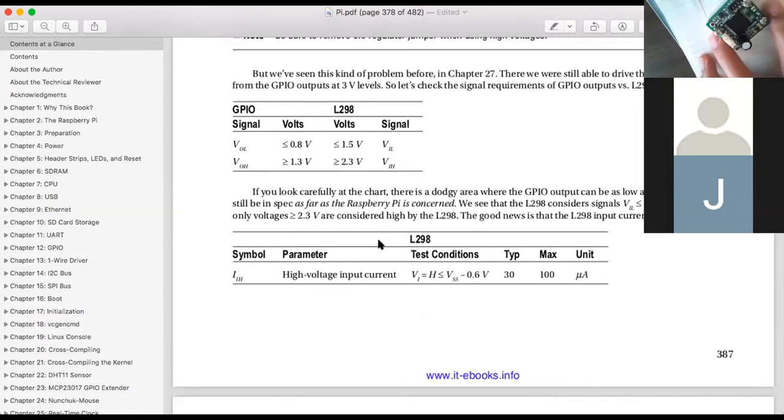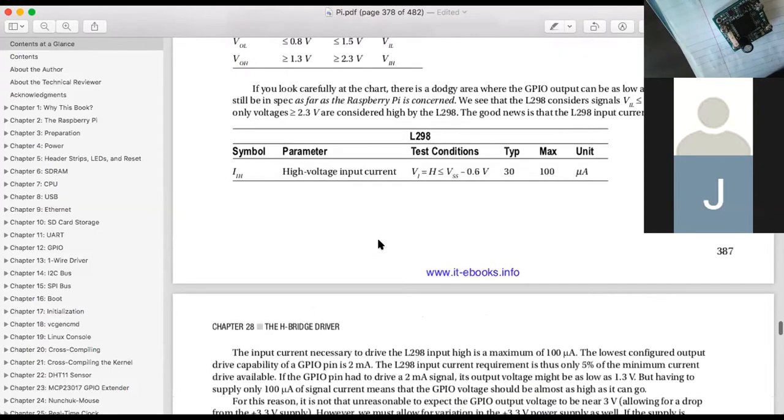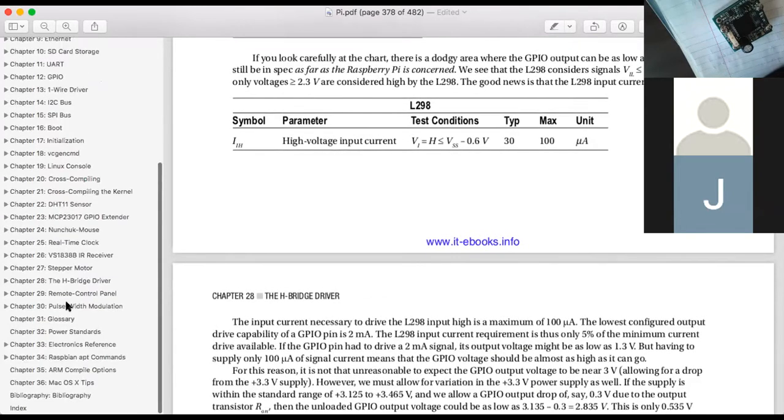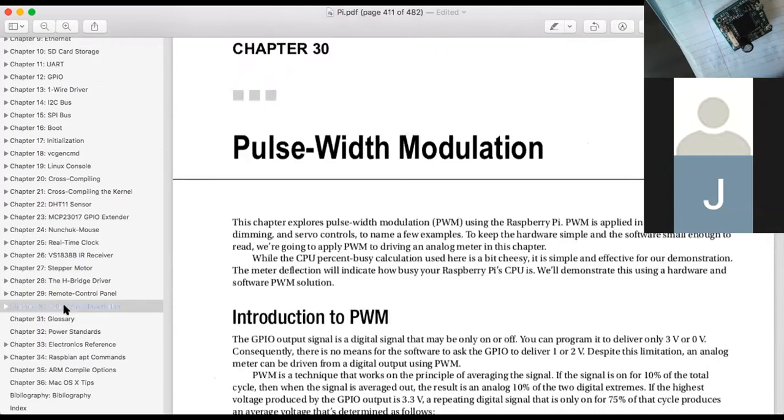So a motor can be a DC motor with RPM. How do we control the RPM of a DC motor? Using an H drive. One quick answer is from the last chapter, called PWM. PWM combined with an H drive will control the RPM of a DC motor.